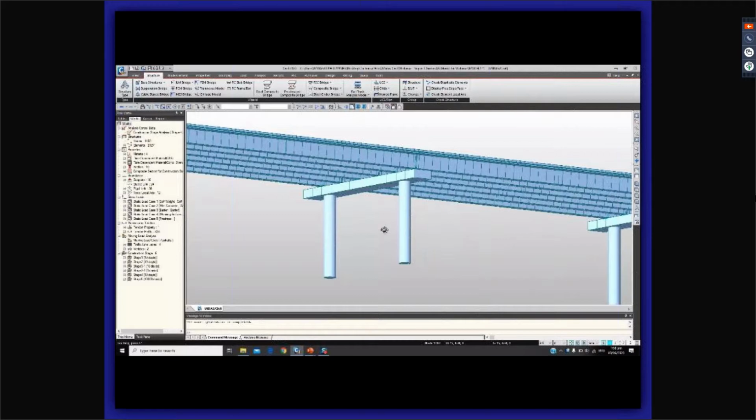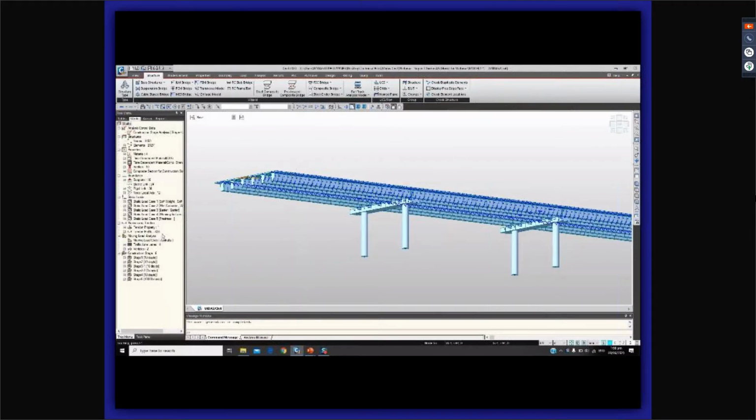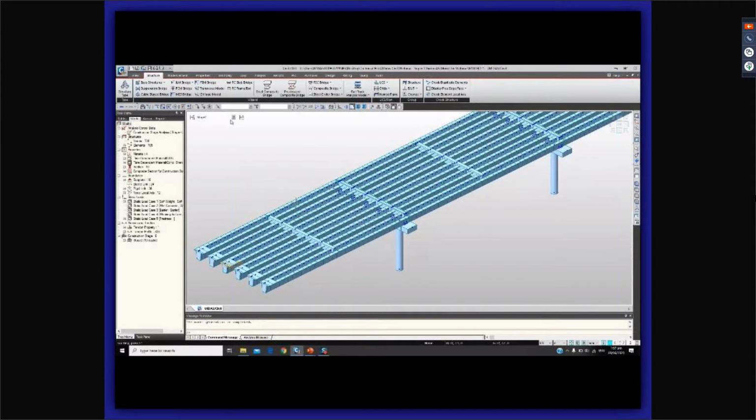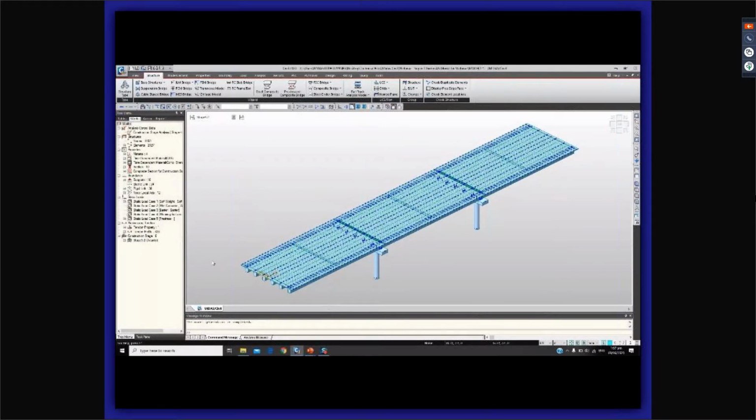So you can see that the end of the girder doesn't have diaphragms. We unchecked it on the section tab, but it has interior diaphragms. And it already inputted two composite sections for the construction stage, the closed super T and the super T section. Then we can now inspect each of the construction stages that it automatically generated. For example, for stage one, it generated the substructure. Stage two, it activated the girders. Stage 3-1, we already have the wet concrete load. And for stage 3, slabs are already activated. And then for stage 4, the barrier and the wearing surface are activated as well.